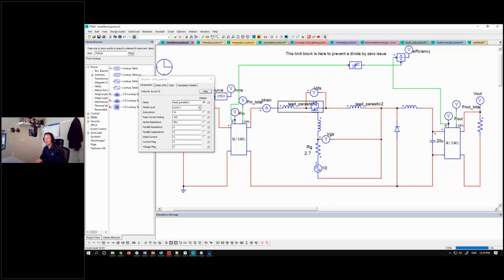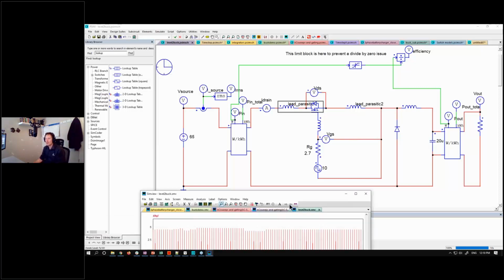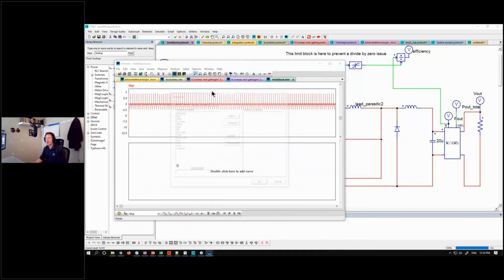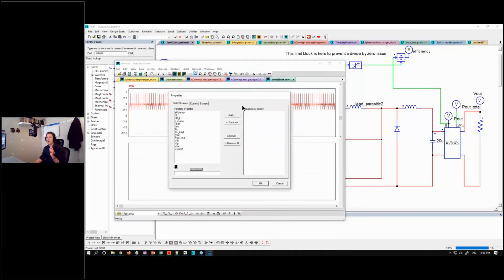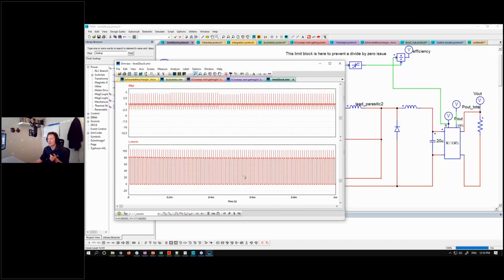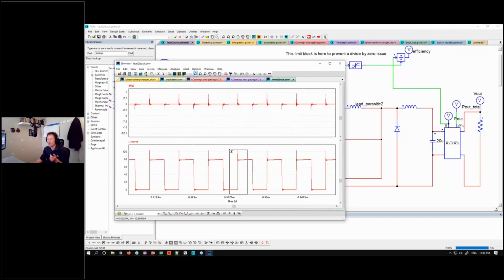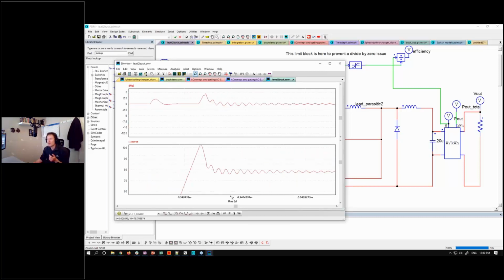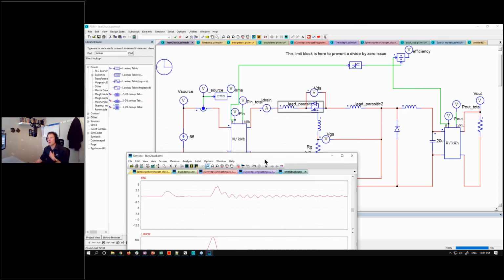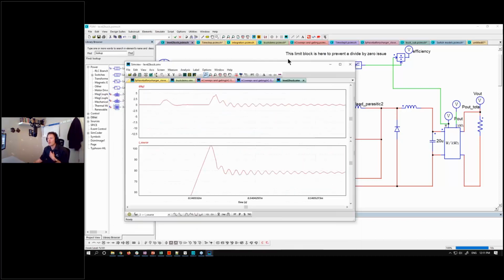If you need them, just put in a small little resistor, an inductor with some series resistance maybe, or leave it off. It doesn't matter. And then here are some results. This is a fairly small time step. Again, because now we're driving and looking at the actual device transition, we care all of a sudden about what that time step is. It should be quite small in order to resolve these small little wriggles here. So this is the current through this MOSFET.